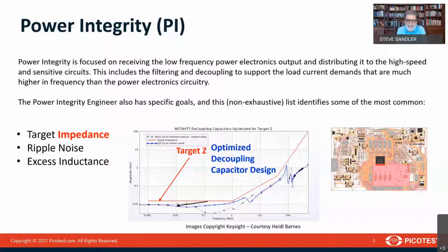These are probably the most important characteristics. One of the things that's really underplayed in power integrity is that there is significant interaction between the voltage regulator module and the rest of the system. While target impedance is focused on the transient response, where the transient is generated by the high-speed ASICs, there are lots of other noise paths from the power supply that also get into the system and need to be considered for power integrity.